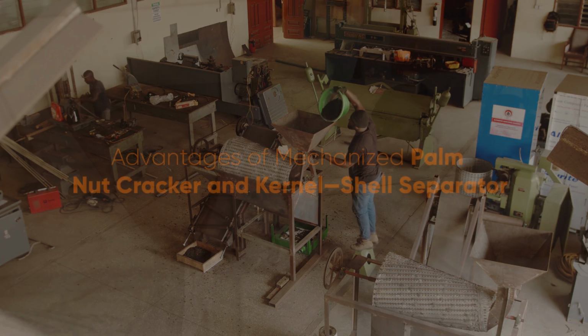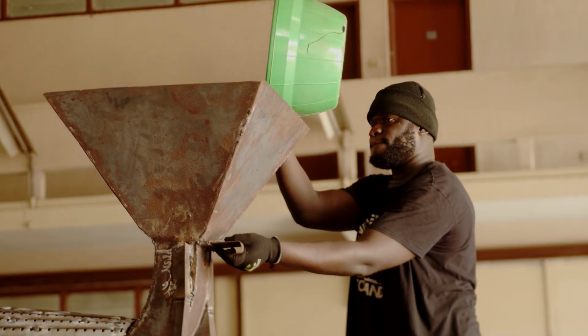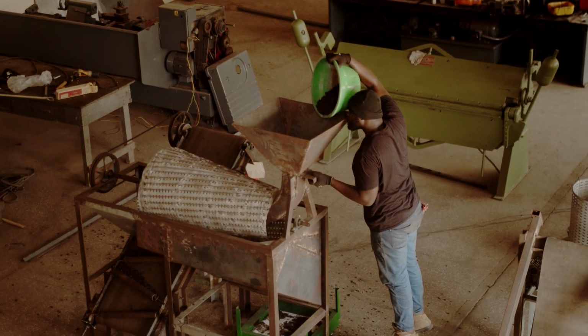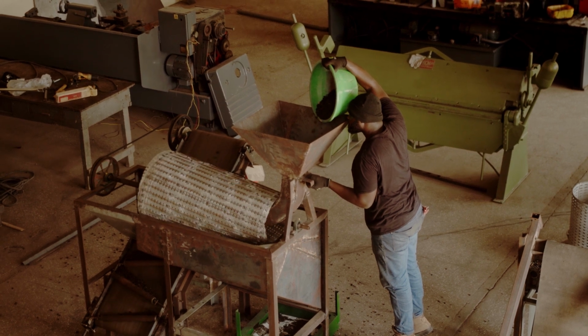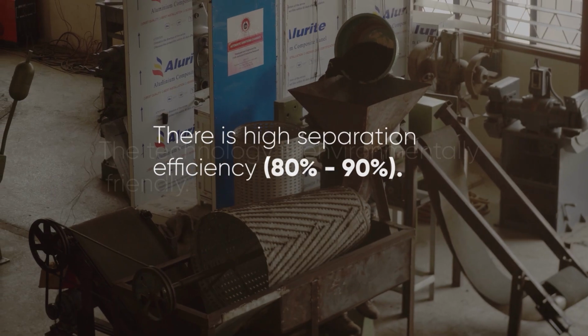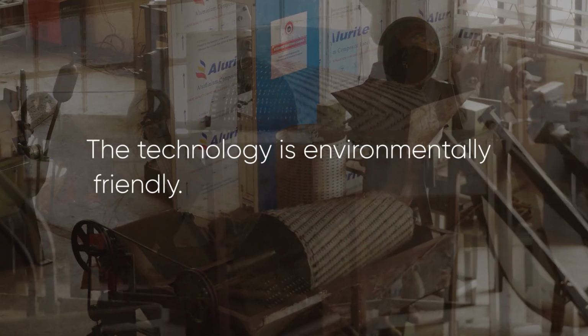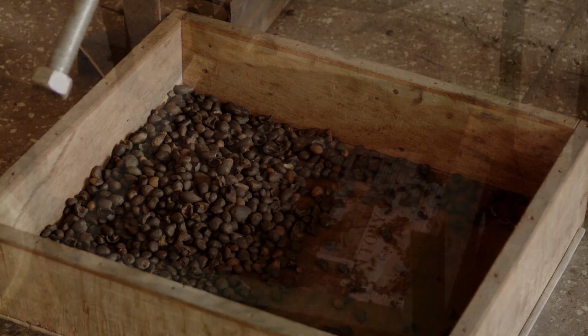Let's also take a look at some of the advantages of the mechanized palm nut cracker and kernel shell separator. The technology eliminates the use of water and clay in the kernel shell separation process. Kernel shell separation time is drastically reduced, and there is a high separation efficiency of about 80 to 90%. The technology is environmentally friendly, and it also produces natural shell pellets, which are a high-grade solid renewable fuel for burning.